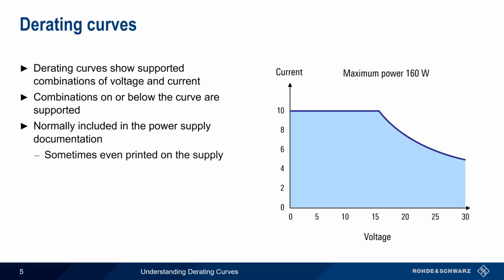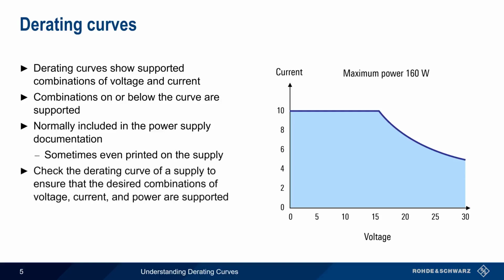In some cases, you may even find the derating curve physically printed or stenciled on the supply itself. Whenever using a power supply, it's always a good idea to check the derating curve to ensure that the desired combinations of voltage, current, and power are supported.